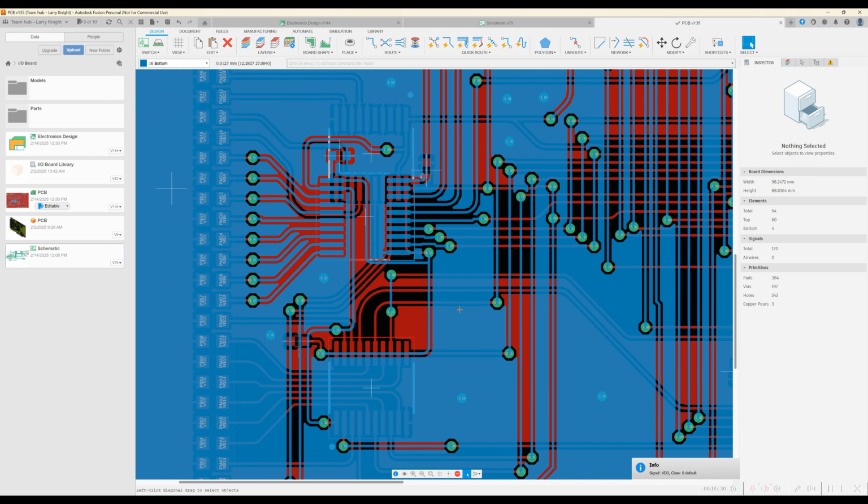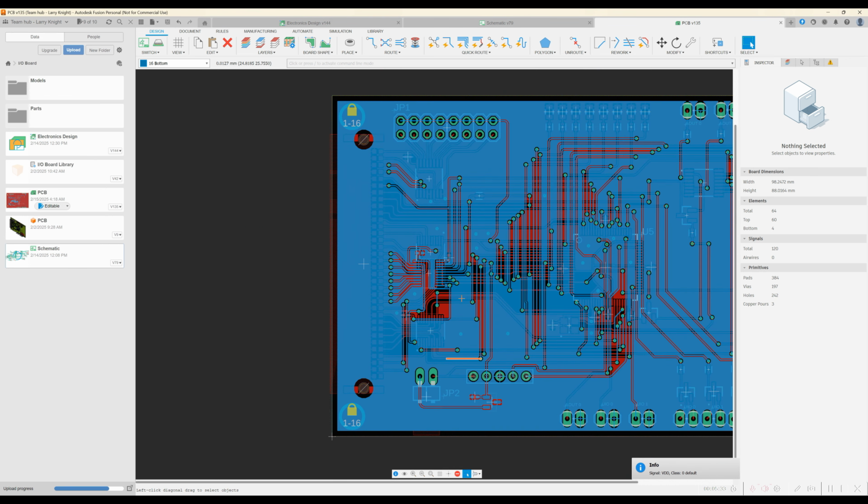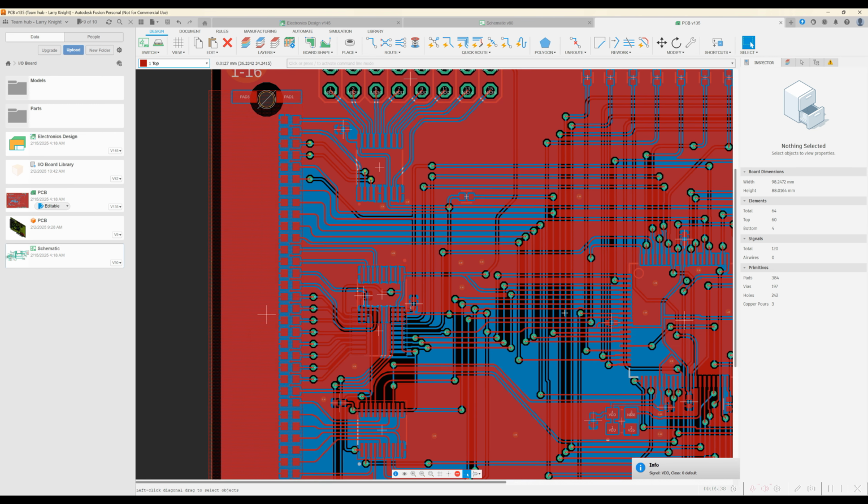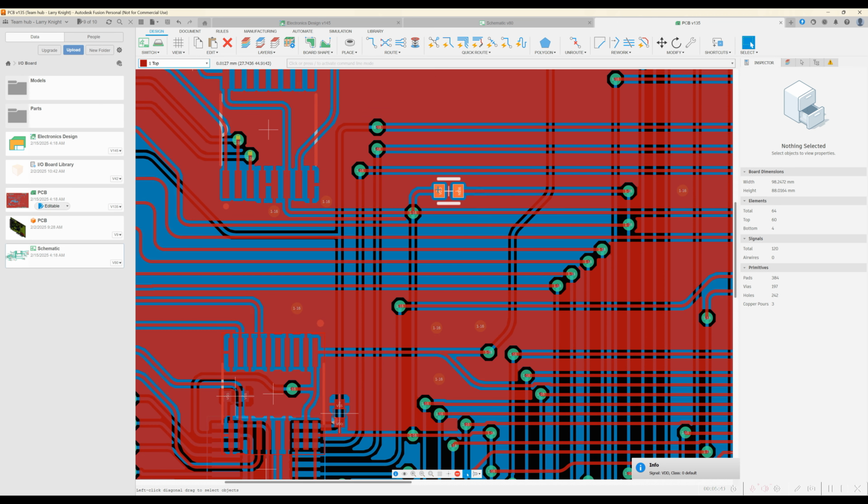And then while we're on the subject of the PCB, this one that we added in yesterday, I'm going to take this out, and this is going to get moved to main brain, so that way it will pull up all the lines from all the boards. Because if we add one of these on every single board, then if you remember Ohm's law, every resistor in parallel cuts the resistance in half. So that's quite a bit of cutting if you have 7 boards on there. That's too much change in the system.